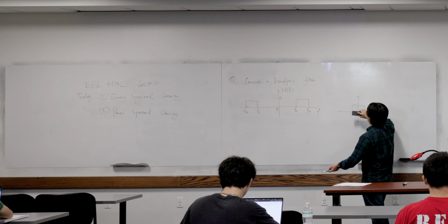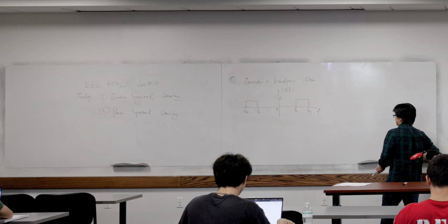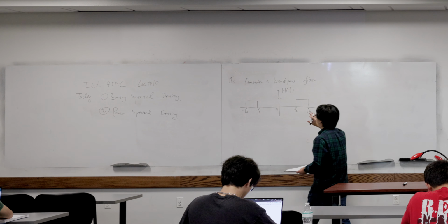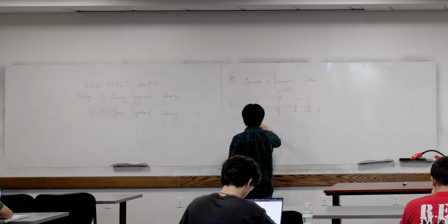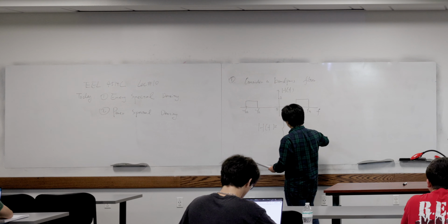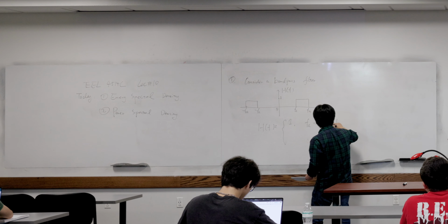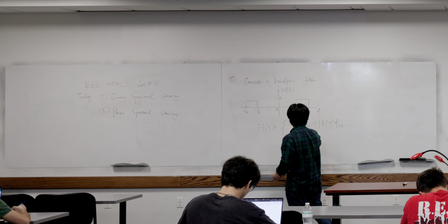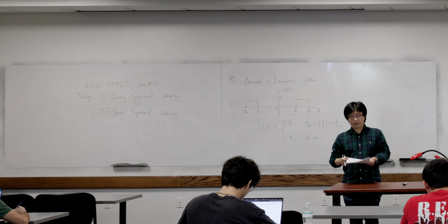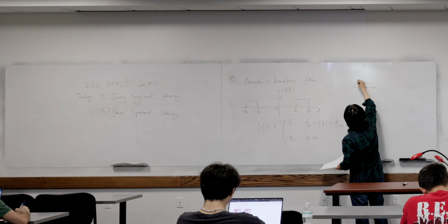Anyway, in lab 1 we used a low-pass filter, but now we're going to use something else. It's a bandpass filter. Mathematically we can write this as a function: H(f) equals 1 when FL is less than the absolute value of f, which is less than FH, and 0 otherwise. So this is what we have, and we'll assume a system like this. Now we consider everything in the frequency domain.